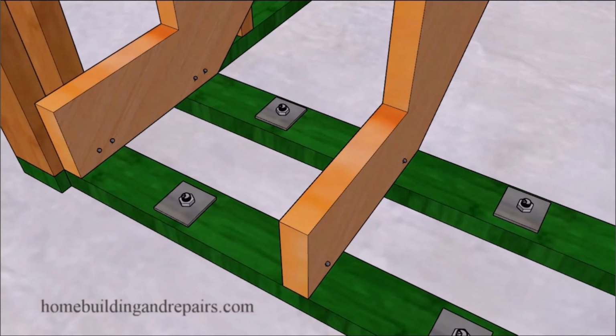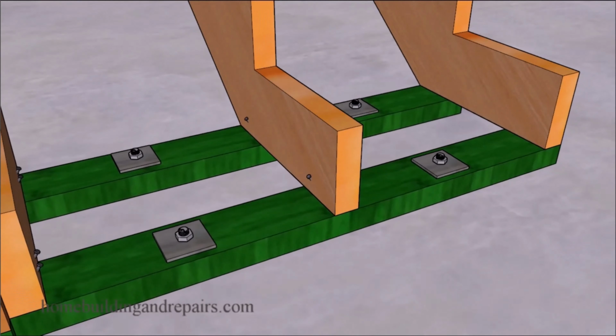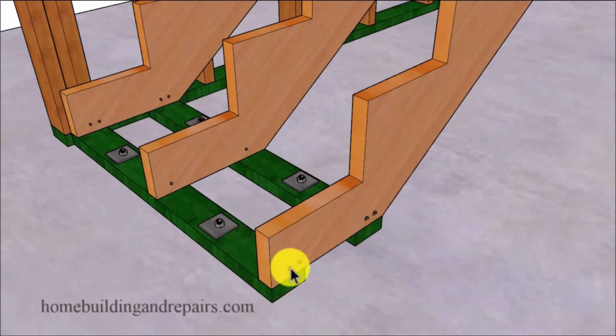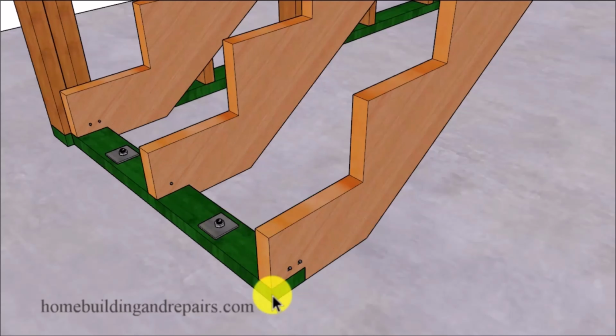For those of you who believe that this design right here won't work for you because somehow the stringers are going to slide forward, even though they're nailed and securely fastened to some base framing plates that are securely fastened to the concrete, or base framing plates that would be securely fastened to a wood framed floor, because either you or the architect think that this is a superior design. I cannot see it, I'm never going to see it, and I'm never going to agree to it, even though I saw this design on almost every set of building plans I worked with.